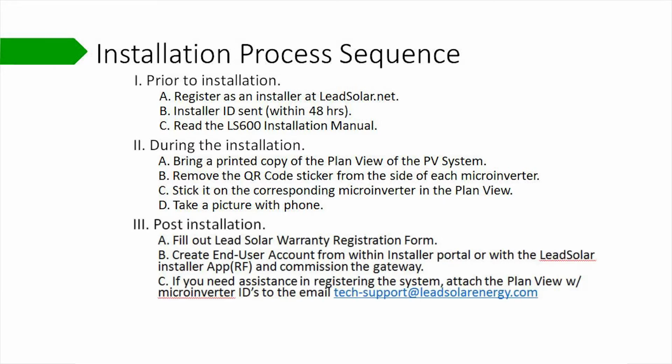3. Post-installation. A. Fill out LeadSolar warranty registration form. B. Create end-user account from within Installer Portal or with the LeadSolar Installer app, and commission the gateway. C. If you need assistance in registering the system, attach the plan view with microinverter IDs to the email tech-support@leadsolarenergy.com.